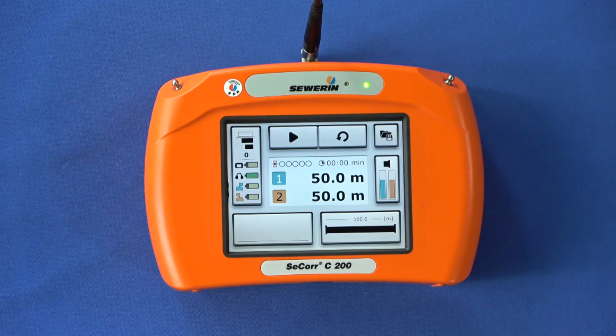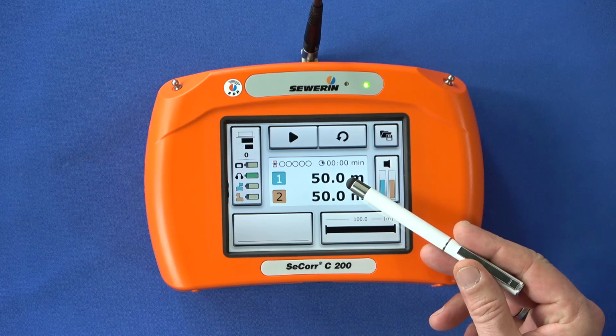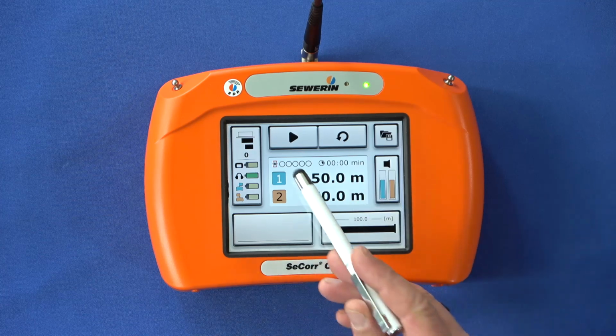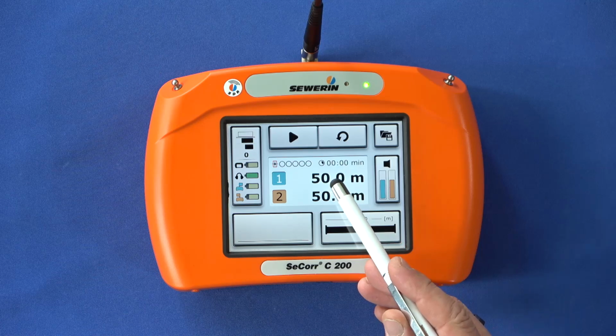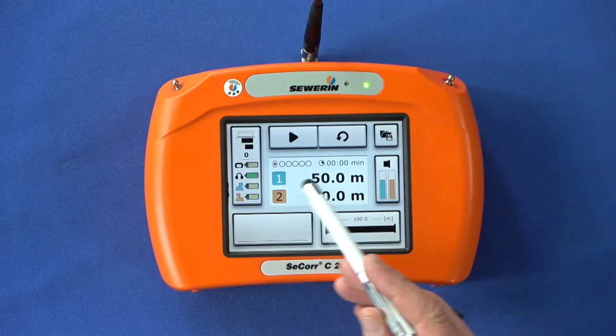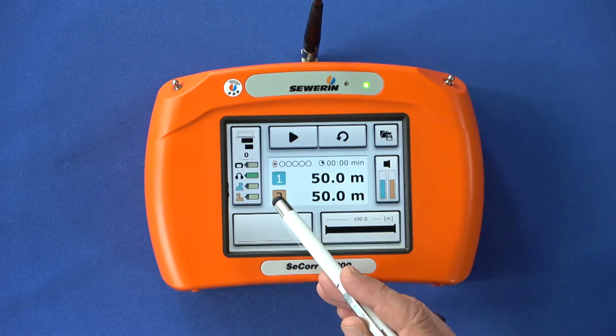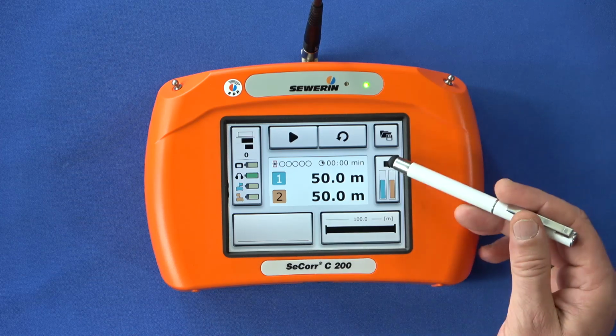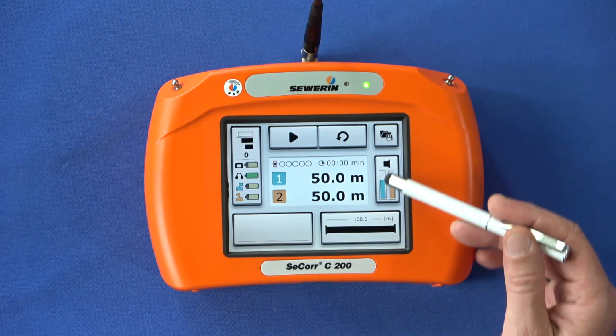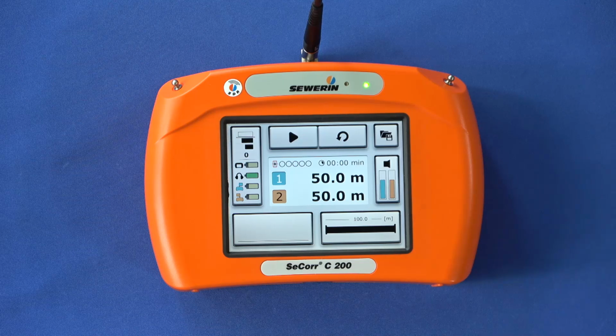In the middle of the screen you can see the results area. The quality of the peak, the total measuring time, and the calculated position are shown here, as well as the distance from both measuring points. To the right of the results area you will see the transmitter button. The current noise level on the first and second RT200 is displayed there during a measurement. This information is updated regularly.